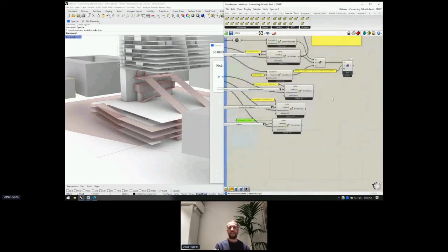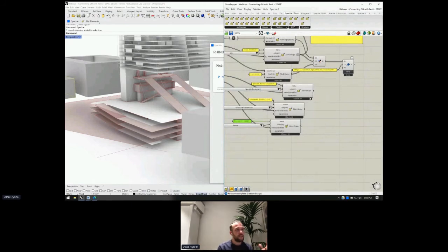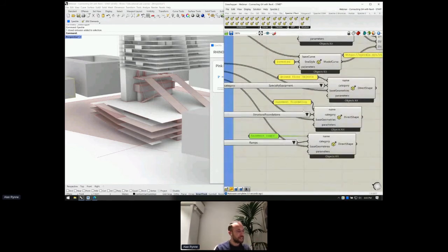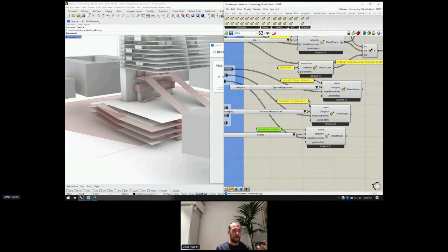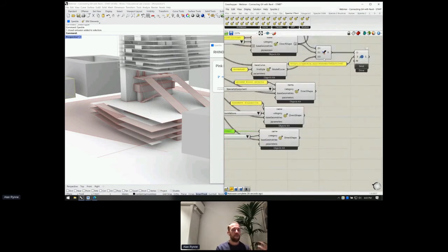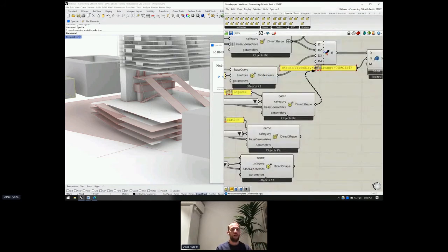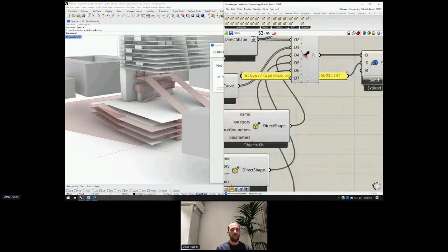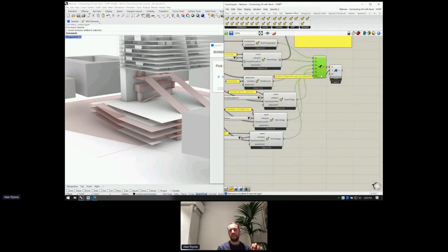Beautiful. So this is like the simplest way to send specific Rhino things to Revit. It's just like sending them as direct shapes, but categorizing them properly. So at least Revit will know how to display them with a specific material, with a specific property. You can filter them accurately. So even if you're not generating real raw native Revit elements, you can still take benefit of the whole categorization and material display by category that works in Revit pretty nicely without having to do a lot of headaches of the actual conversion to native Revit elements, which we're going to see in just a sec.